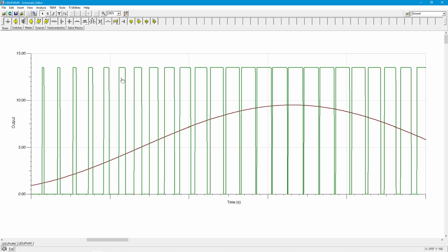And what we're going to do is use these green pulses to drive an LED or to drive a motor. We'll have a switching transistor, basically. In the case of larger currents, obviously, it'll be a power transistor. But we're going to use this logic signal. I mean, this might be a 5-volt signal. It could be some other level. That's really not too important.